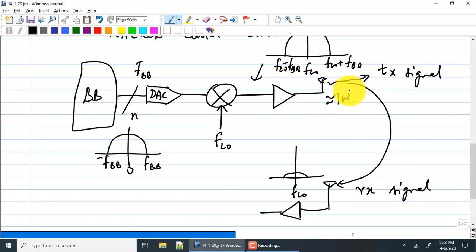If you take a base station, for example, which is on top of a tower, that typically transmits tens of watts, 10 watts, 20 watts, 30 watts, numbers like that. They are typically slightly further away from the person, but even this 1 watt is quite high. So this amplifier on the transmitter side is called a power amplifier. You are dealing with much higher powers.